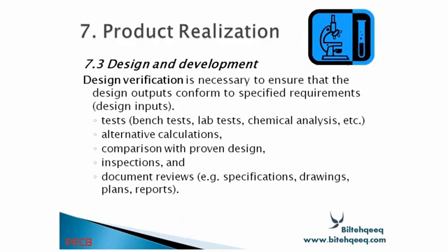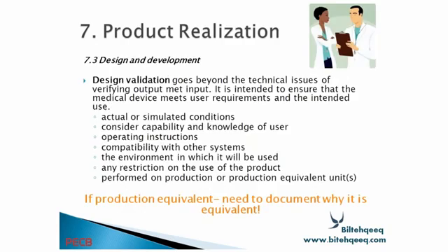And now we will talk about design verification. Design verification is necessary to ensure that design outputs conform to the specific requirements. Design input, test, bench test, lab test, chemical analysis, etc. Alternative calculation, comparison with proven design, inspections, document review, for example, specification drawings, plan and reports.